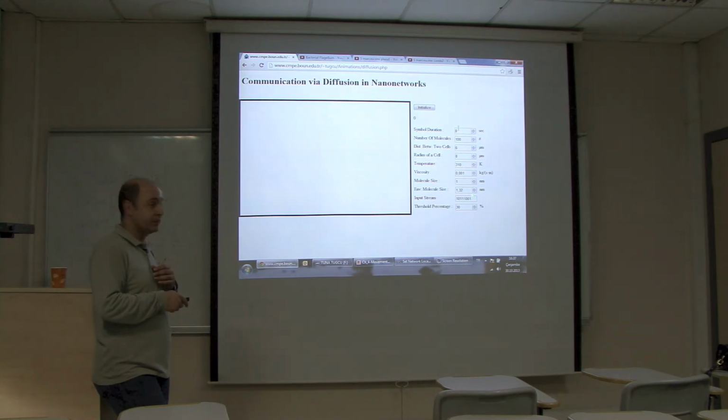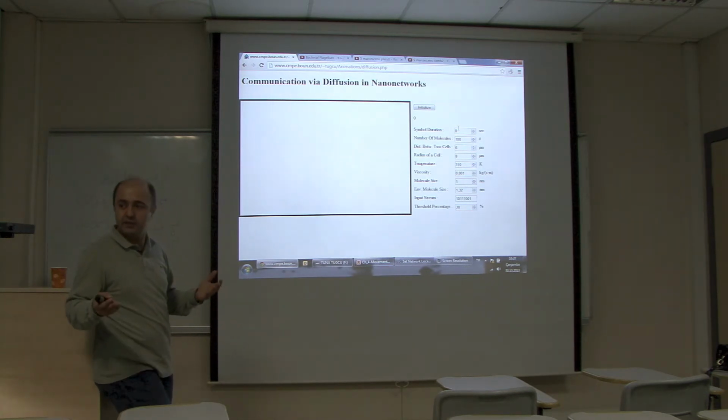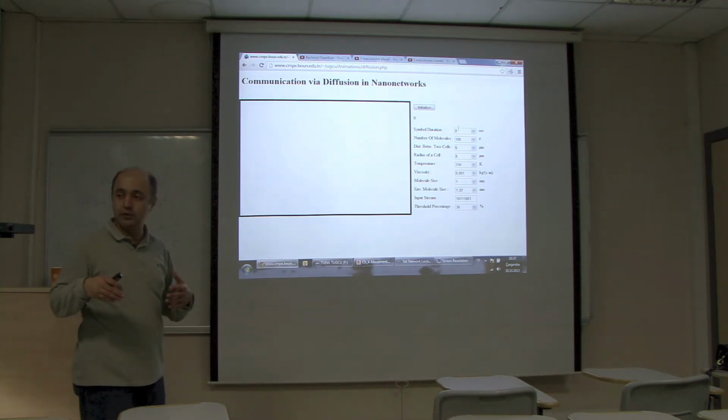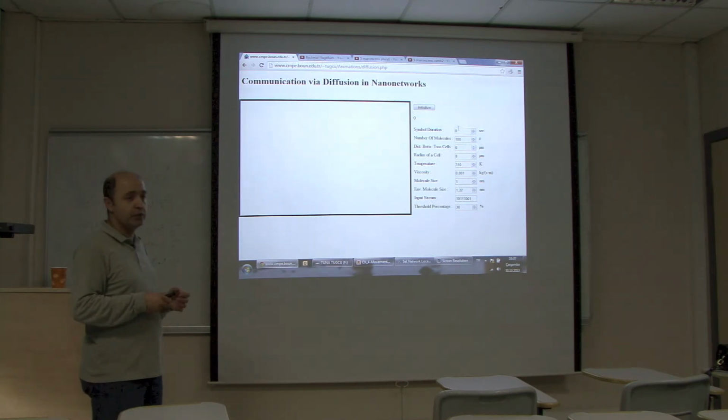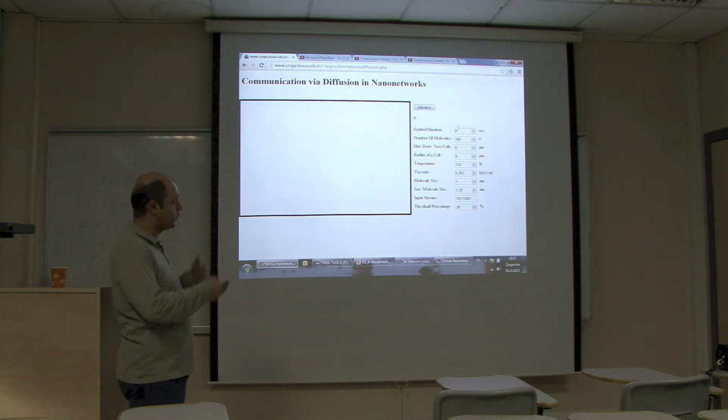The input stream we're going to send is 10111001. You can change it. You can send anything you wish. And the threshold percentage: you're sending 100 molecules. If 30% of them are received, you assume 1 has been sent. Otherwise, it's a 0. You can play around with all of these so that you can see the effect of symbol duration, the effect of the number of molecules being sent, the effect of the threshold, whatever.